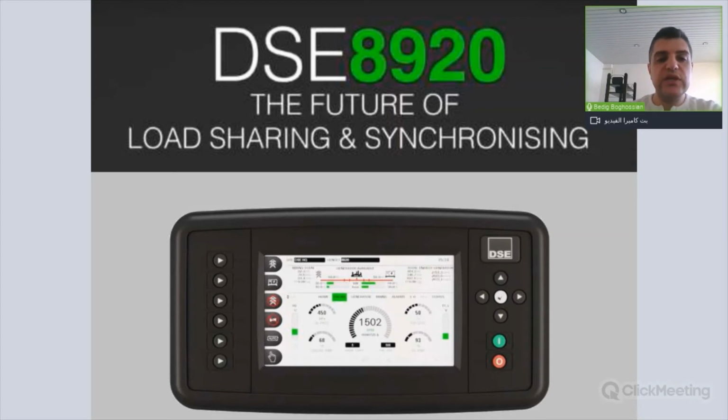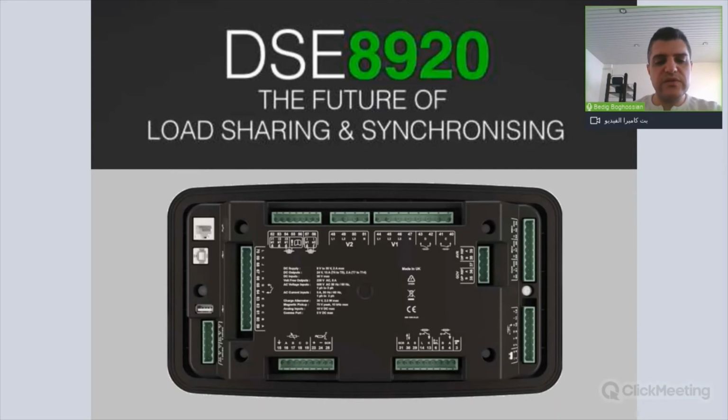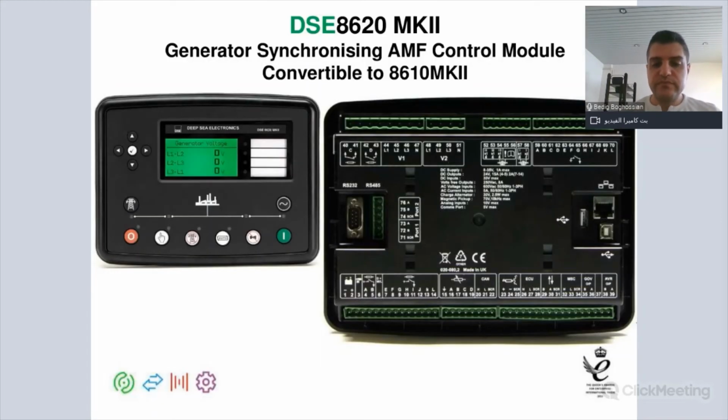That's the 8920, which we spoke about. It's a new controller. It has a 7-inch color display. So it's for special requirements where you need to have a large screen view. And from the back, it's very similar to the 8610. So the terminals are the same, but with different positions. But it has all the terminals that the standard 8610 MKIII has, except for the RS-232. So the 8920 does not have an RS-232.